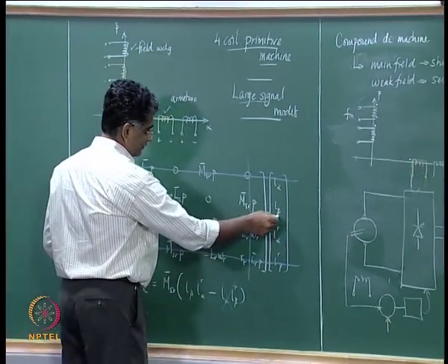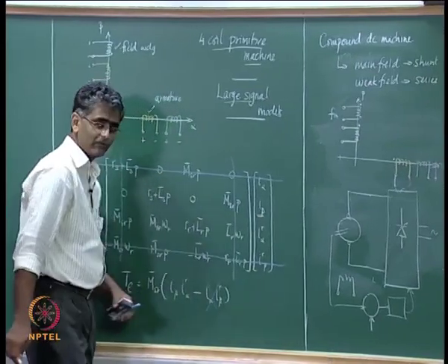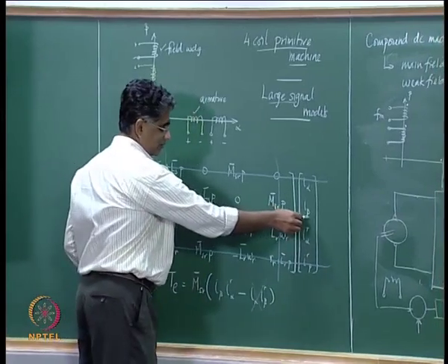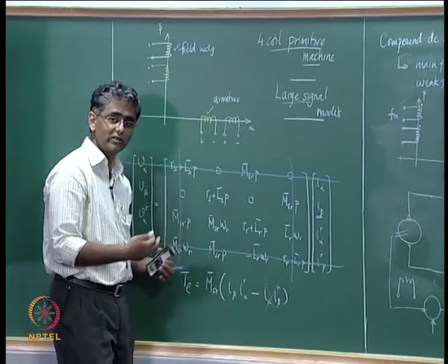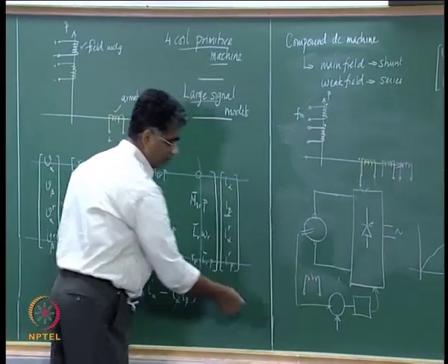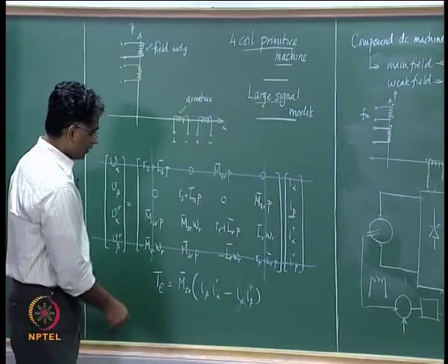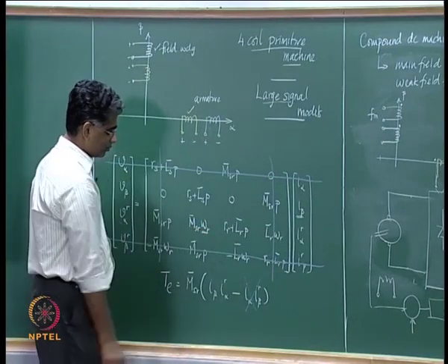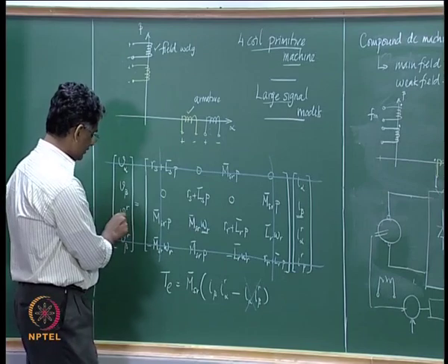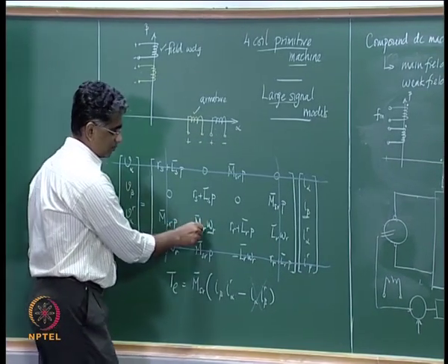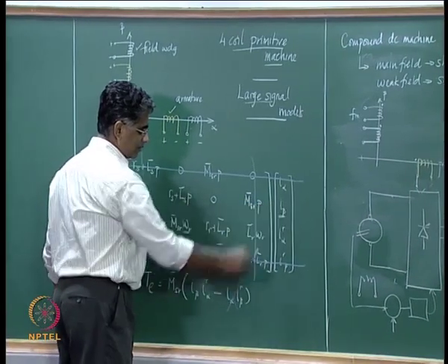Because you have this term I beta, the field excitation, which may change in a general DC machine. If you put a controller here as well, it could change, and then that is going to be multiplied by this omega r. You see this equation: the armature voltage equals the speed EMF term multiplied by this I beta.